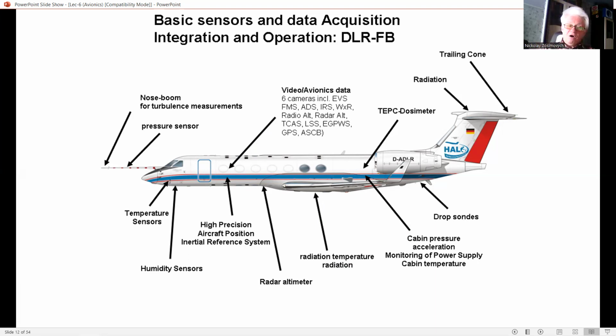The blending of normal acceleration and pitch rate is sometimes referred to as C times M, star control. The blending of pitch rate and normal acceleration to meet pilot handling criteria is, however, a more complex subject and beyond the scope of our lecture.